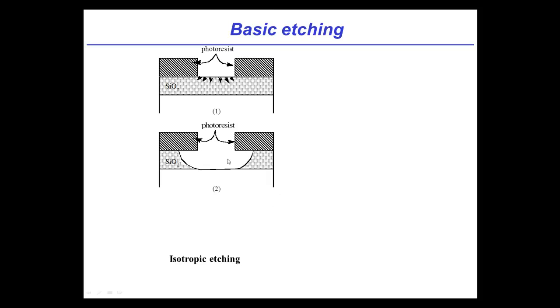There are other examples. Certainly there are examples of plasma or dry isotropic etching. An example of that is SF6, or sulfur hexafluoride. But anyway, what you see is that it etched away, and since it's the same in all directions, it doesn't just go down. It goes down, but as soon as it goes down a little bit and sees some exposed silicon here on the side, it'll start going under. So it's going to etch like a circle, kind of centered in the middle here, or something circular based on these areas.